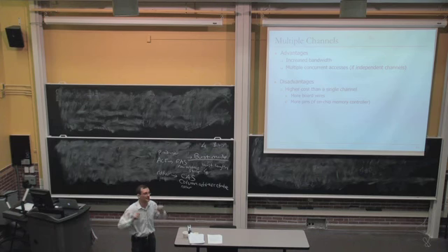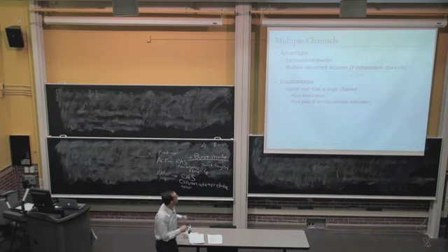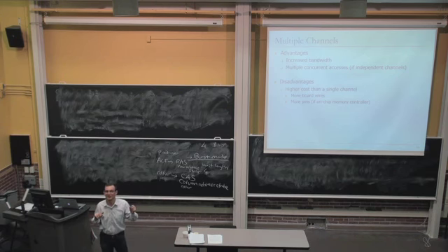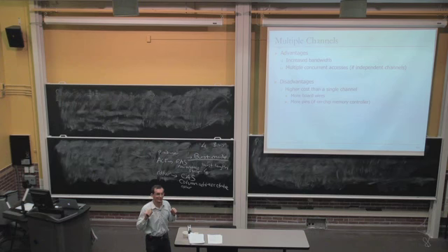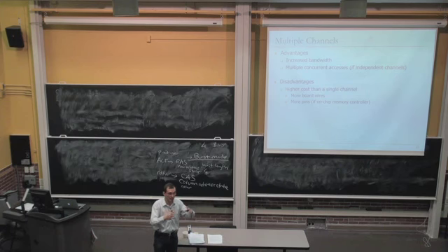As you increase the number of channels, as you increase the number of banks, you get more concurrency. That's why as manufacturers put more cores on chip, they also try to put more channels. Of course, the downside is it's not as easy as putting more cores, right? Putting more cores, you're not increasing the number of pins that you need on the chip. Whereas if you want to put more channels, now you need to add more pins, right? This is what makes scaling a chip to a large number of cores difficult, because as you put more cores, there will be more demand.